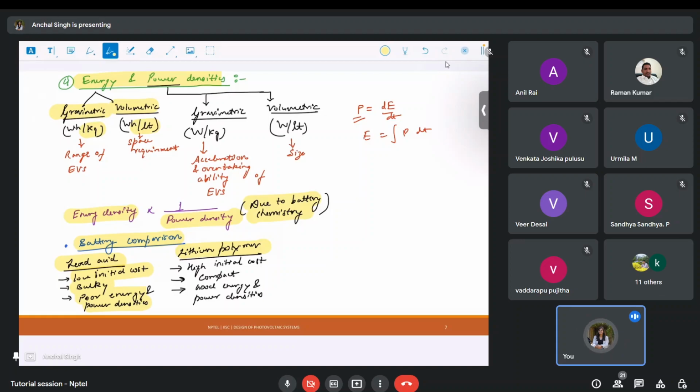But when I'm designing an electric vehicle and I want to increase the range of my vehicle, I need to reduce the weight of my vehicle, then I would rather pay more money and make my system compact, right? So that is both extremes. And these lithium polymer batteries have good energy and power densities. In the curve that sir has shown in his lectures, you have seen that there is a table where they both are at the extremes, and the rest, the nickel metal hydride batteries, are all in the middle. So you just have to remember this rough pattern of these batteries. That's it.